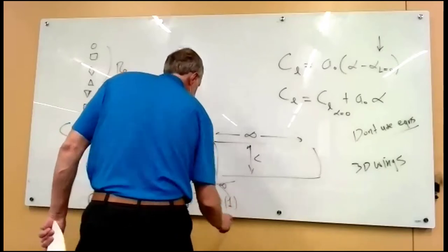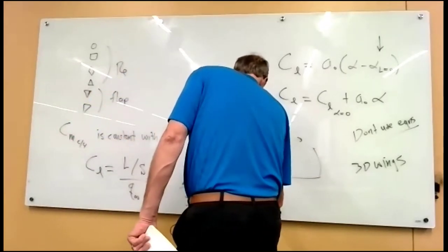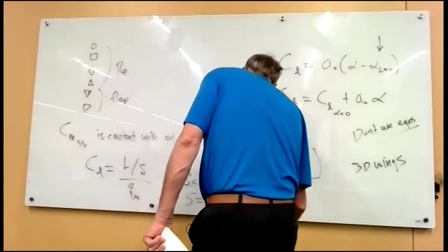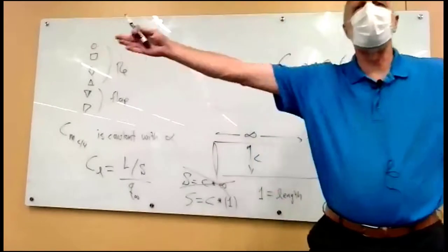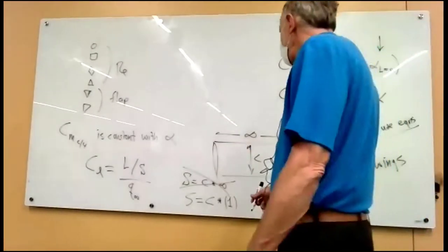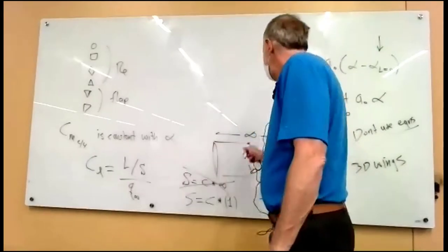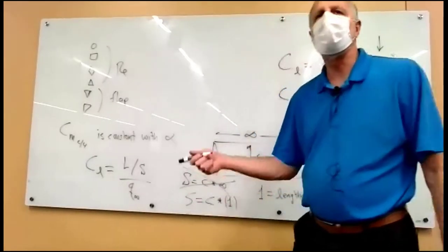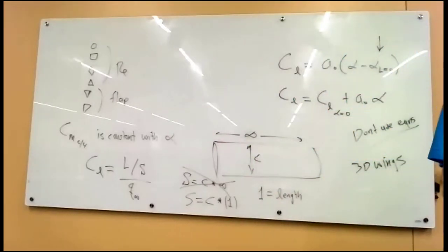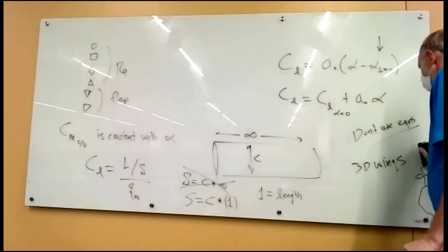So we just put 1 in for the length. So what that means is you get lift per unit length. So if you're working problems for an airfoil and you need to calculate an area S, you just take the chord and multiply by 1, and that gives you the area. So it's lift per unit span. All right, next, let's do the example.